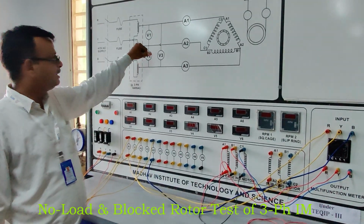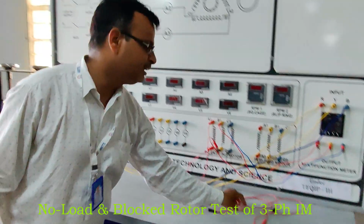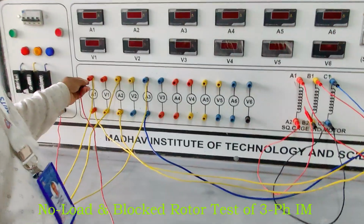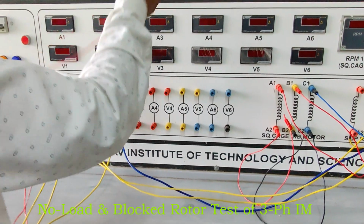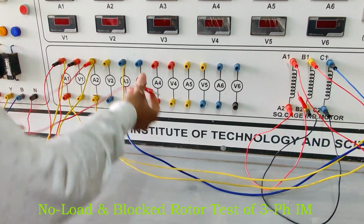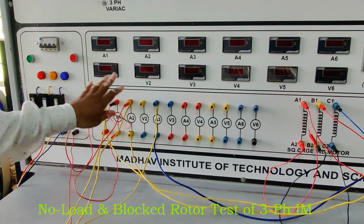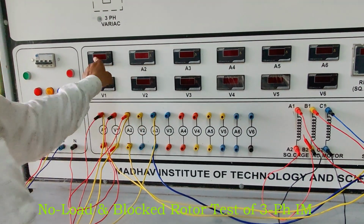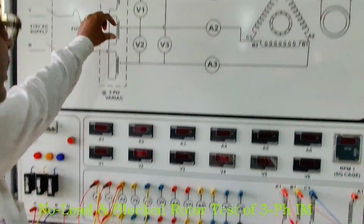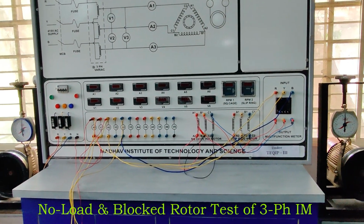Second, we have to connect a voltmeter here. We connect the voltmeter across two lines for measuring line to line voltage. Line to line voltage means you connect across two lines, A1 and A2, at the V1 terminals. We then observe the readings of A1, A2, A3 for the line current, and the V1 voltmeter for the voltage. So this is the complete circuit for performing the no load test.